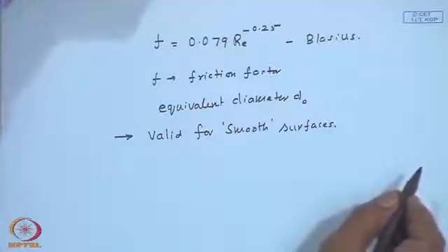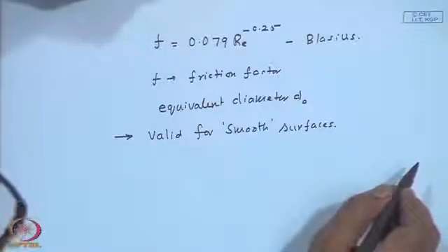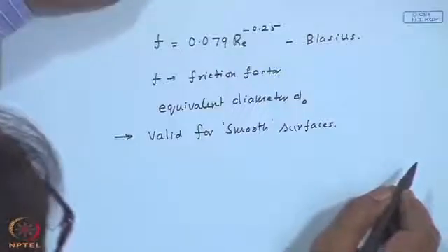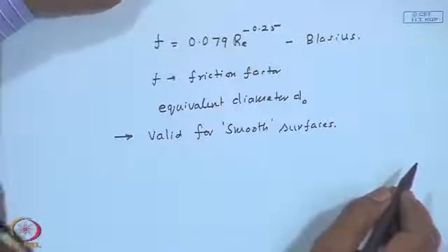So, we have methods or the formula to calculate the heat transfer coefficients in the air ducts and the friction factor, and hence calculate the pressure drop in the air duct and find out the pumping power needed and compare with the energy gain, and make sure that the energy gain is significantly more than the pumping power required.